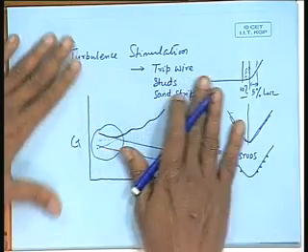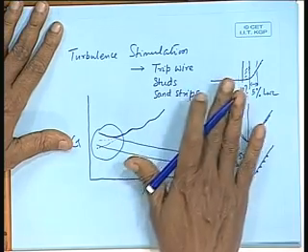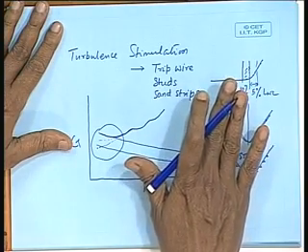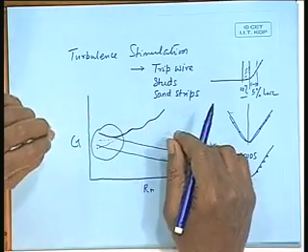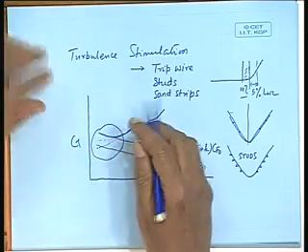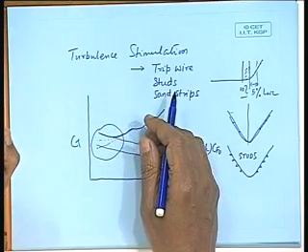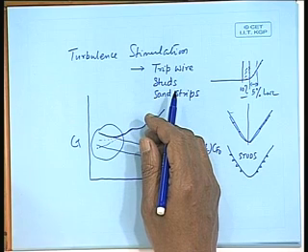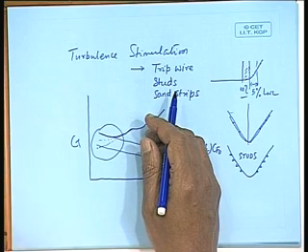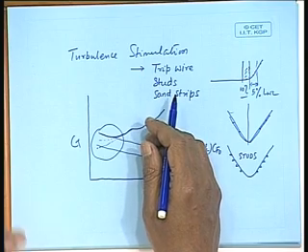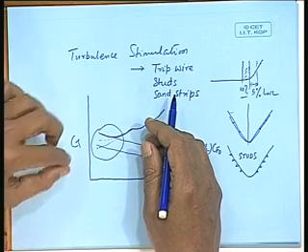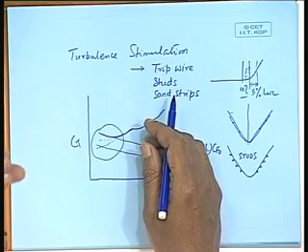Now, all these things I am telling is very simple to hear on the drawing on a piece of paper. Actually, when you do experiments, the resistance at low speeds is very low. So, if the measuring equipment has a small, constant error, then that reflects here maximum, because the quantity we are measuring is small.